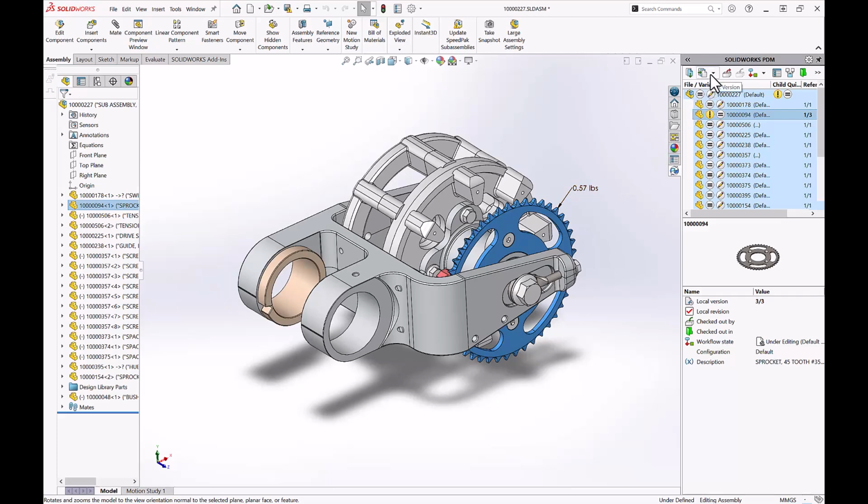So using this Get Version tab here, I can see when it was created, my second version, and my third version. Notice that on my second version, I didn't leave a comment. This is giving me minimal information about what this version really is. For version 3, I left that slots comment, which created the description of the version. So it's best practice to leave these comments so that we know which version is which.